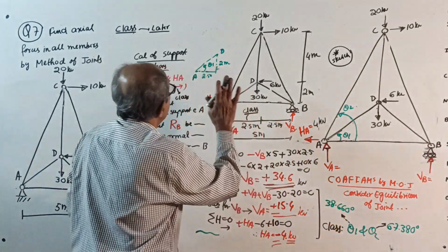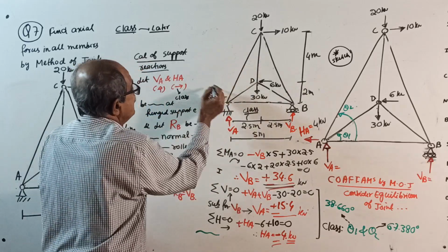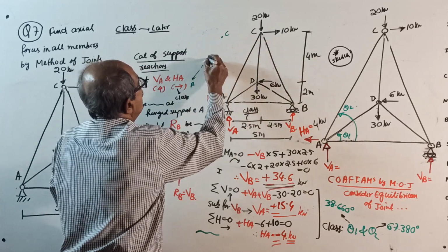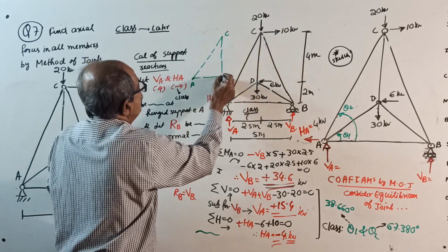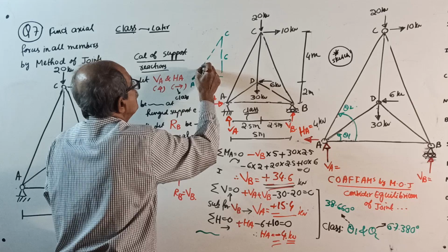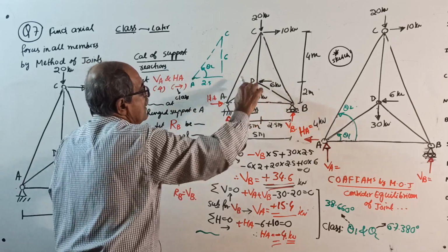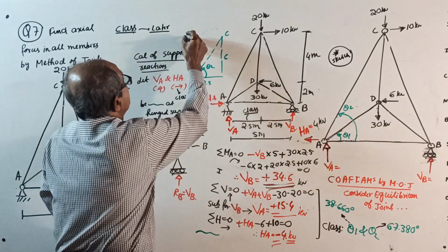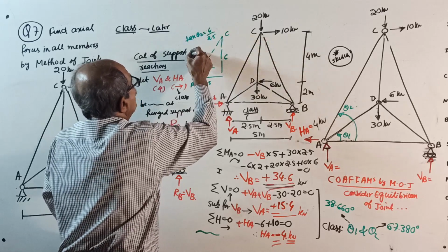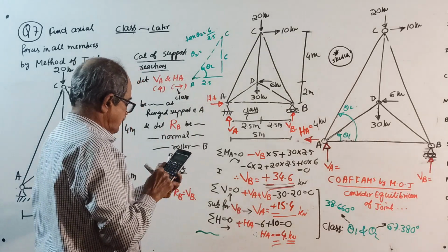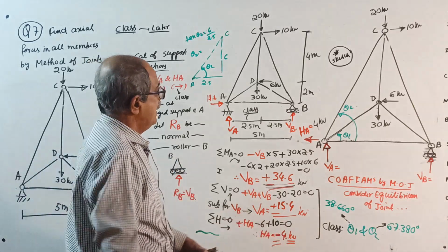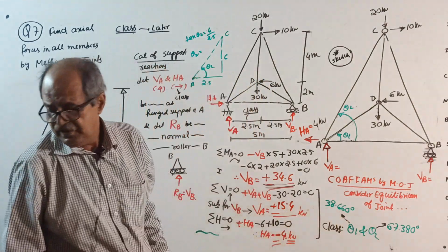38.660 degrees. Okay. Same way, next, prepare one more sketch. Once again, mark A here, then mark C here, this way. Now this is 2.5, but the height is 6 meter. This angle is theta 2. Tan theta 2 equal to 6 by 2.5. Calculate theta 2: 6 divided by 2.5, shift tan inverse, answer 67.380 degrees. Okay, I wrote it there. So show the calculation and get the answer.